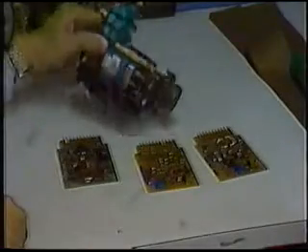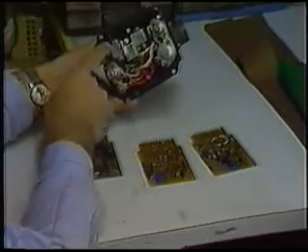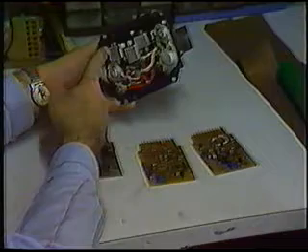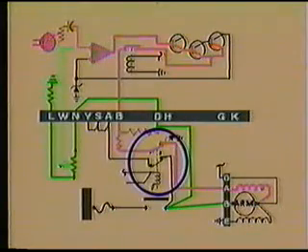The reset relay is internal in the control panel, and its tripping function is controlled by the fault circuitry within the control panel. The generator output relay has already been discussed and is controlled by the starting circuit. If either relay has opened, no signal will be provided to the A lead, and therefore the generator will have no output.